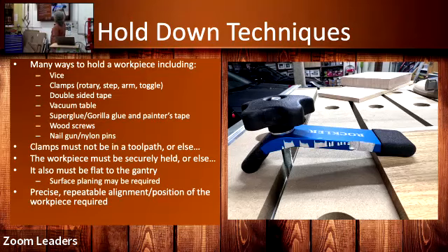Notice the etching on the side. One of the things that you see on preview is where the tool will start, and then it zips across to where it's going to start cutting. So if you remember that preview, you won't put your clamp in that path. You can say, go way up here and then come over and come down, but that takes so long. You just want the fastest path. I could show you the clamp that Dave etched on my machine too, but I didn't want to embarrass him, and this one's effective enough. So keep your clamps out of your tool path.